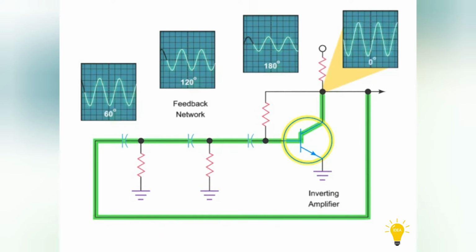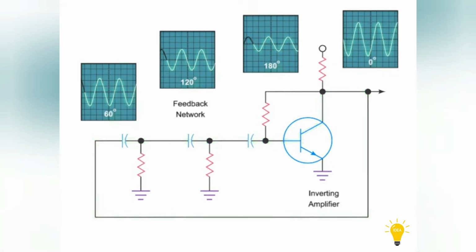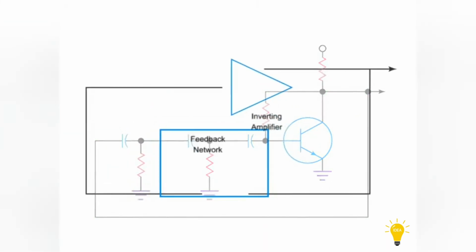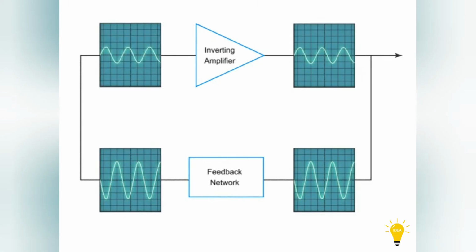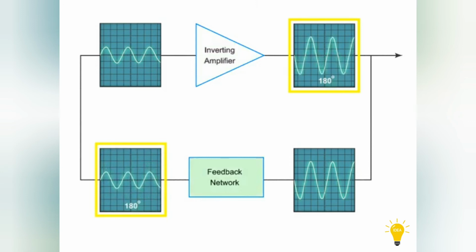back into phase. In order for the oscillator to produce a repetitive oscillating electrical signal, it must follow two criteria. The circuit must have a loop gain that is greater than 1, and it must maintain its phase state. The phase state is sustained when the inverting amplifier's 180-degree phase shift is reversed by the 180-degree phase shift of the feedback network. Thus, maintaining the phase state is accomplished by a 360-degree change in the phase as a result of the 180-degree signal inversion at both the inverting amplifier and the phase shift network.